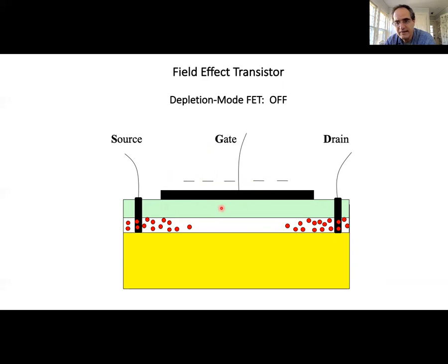And because semiconductors, even heavily doped semiconductors, have a rather small concentration of electrons compared to a metal, it's possible to do this even with a moderately large gate voltage. And in this way, we can switch the semiconductor from on to off by applying a voltage. So you can see this works in much the same way as the triode does. It's actually a rather simple device.